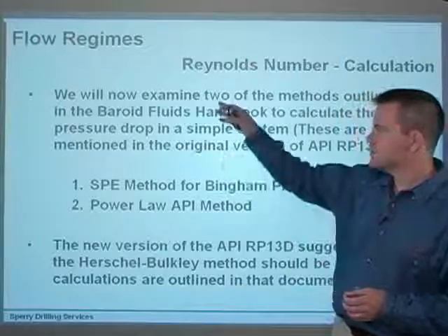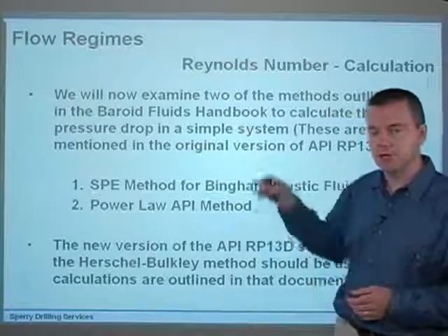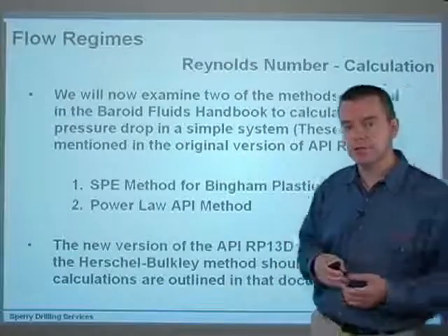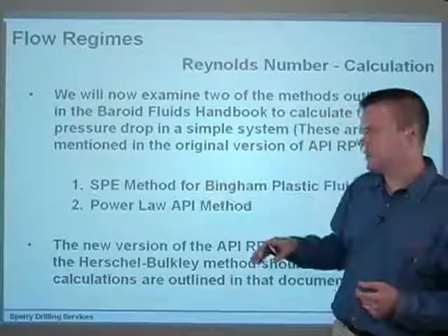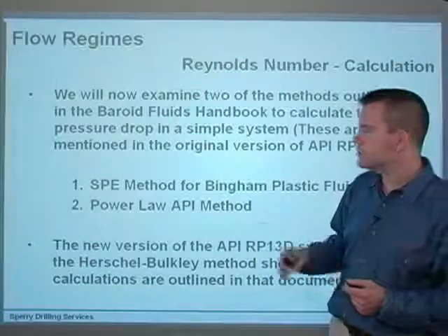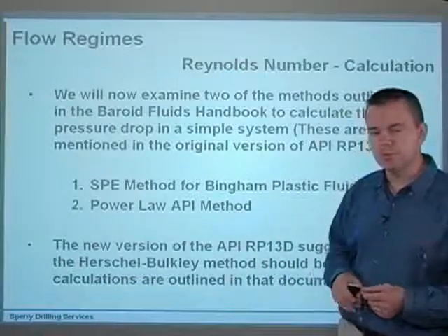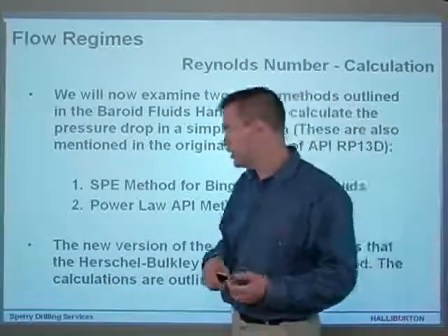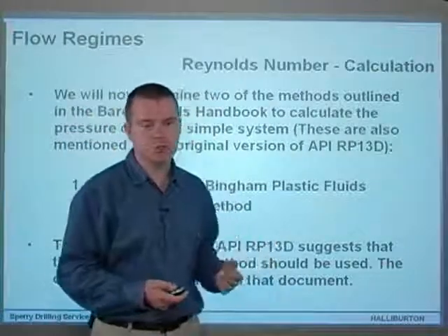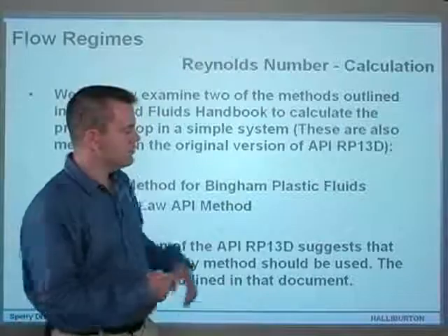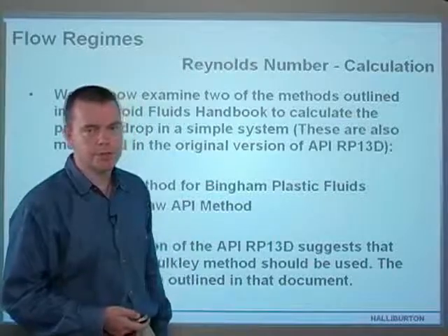Basically, I'll talk about the two versions that were in the Baroid Fluids Handbook, Chapter 9, and API RP13D right now. It's easier to talk about these two because they're much simpler equations. Talk about the SPE method for Bingham plastic fluids and the Power Law API method as well, and go through some of the equations and show you how they're derived, just to give you a feel for what goes into the calculations.